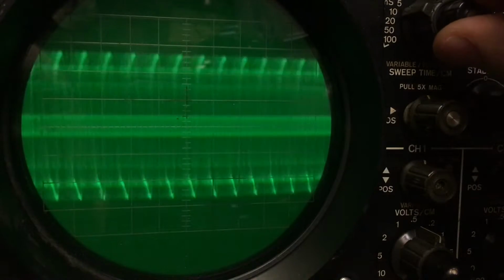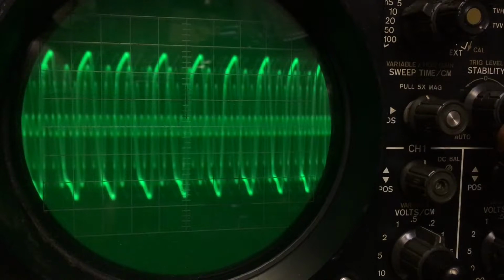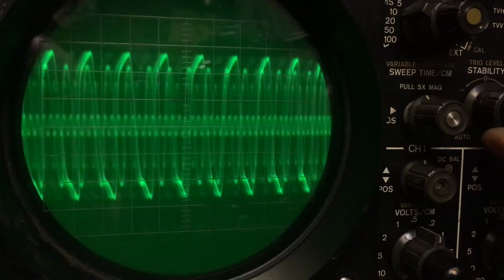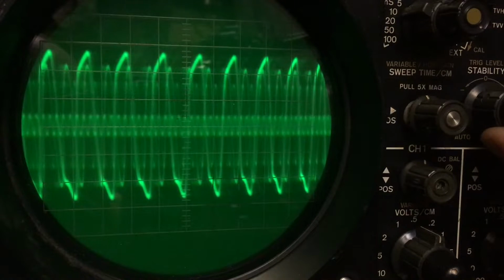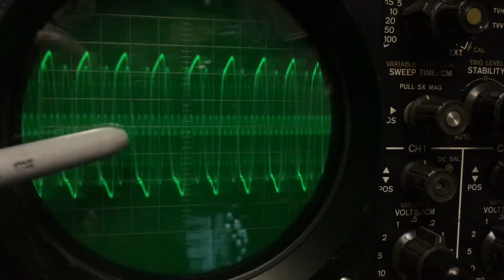And if I run this same series of step signals, I almost said step sticks because I have 3D printers on the brain. Anyway, if I run the same stepped signal into the front end of my 10 megahertz scope, obviously running from 2 megahertz to like 20 megahertz is going to clobber this front end, and it can't keep up speed-wise. So even on the 2 megahertz signal on the 10 megahertz scope, we're going to be rounding off our square wave, and you can see the drastic change in amplitude when we go up to 20 megahertz. And this segues very nicely out of our theory segment and back into our handheld oscilloscope.